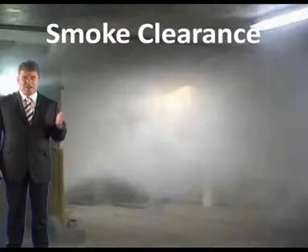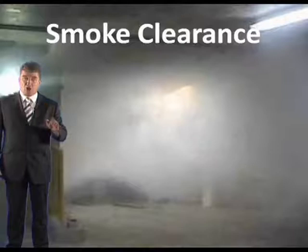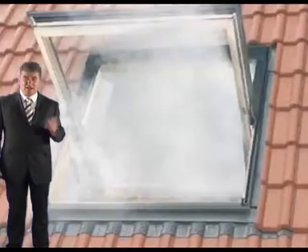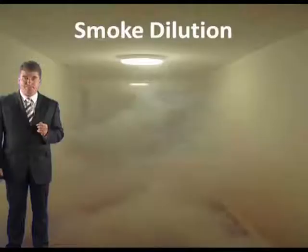The next system I'm going to look at is smoke clearance, and this method involves removing relatively cool smoky gases from a space in a building when smoke is no longer entering or being created in that space. In other words, post-fire. This can be achieved by providing natural cross-ventilation, for example, opening windows, or by the activation of powered exhaust systems. In the fire brigade, they use positive pressure ventilation, where they put huge fans and push out all the air. They can either be passive or active. That's generally carried out afterwards to get rid of the smoke.